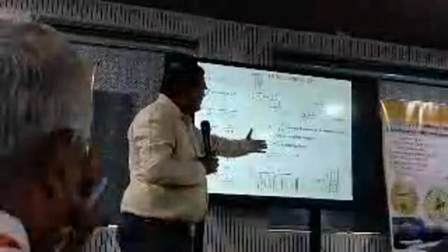So this is the equation of motion we call, and this is the equation for the amplitude of the vibration: F naught by k, over the square root of (1 minus r squared) squared plus (2 zeta r) squared, and tan phi is equal to this component by this component. Finally, this is the equation for amplification. Some of the equations are for transmissibility. These mainly depend upon the natural frequency, root k by m, and the damping factor, c by c naught. So finally, these are the equations for that.